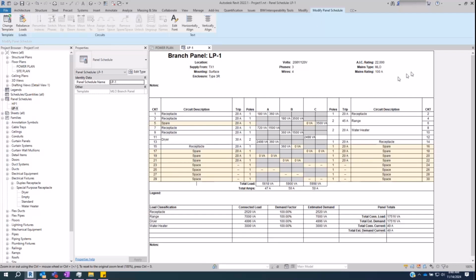When you look at the mains rating, the mains rating is 100 amps for this one, 100 amps for this one, and 100 amps for this one. And that's why we say, hey, look, instead of having three 100s out here, each mains rating is the same to itself, which is 100 amps. So that's why we say there is a 100 amp panel board here.